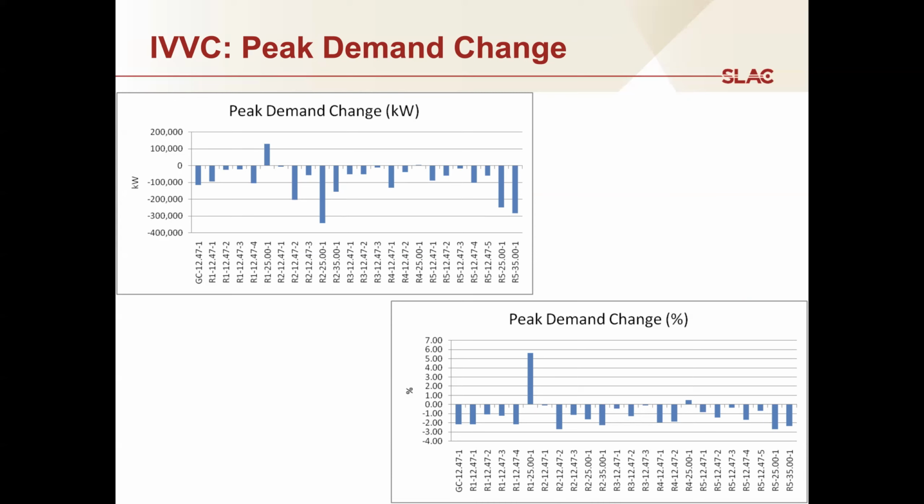Basically, they look like the load increases with voltage. So think about, for example, if I have a thermostatic load and I decrease the voltage, you might expect the thermostatic load to run longer, right? And that might result in a behavior that's unexpected. So you can see, depending on the nature of the load, there may be increases if you exercise volt-VAR control. In other words, you raise the voltage or lower the voltage.